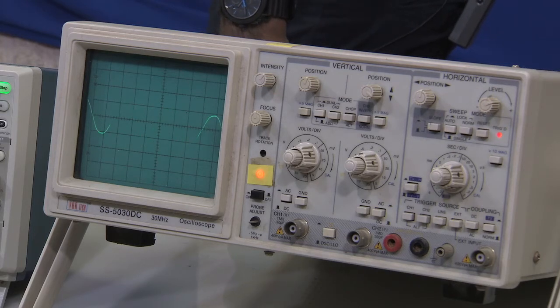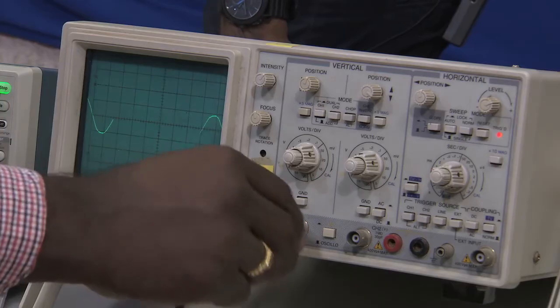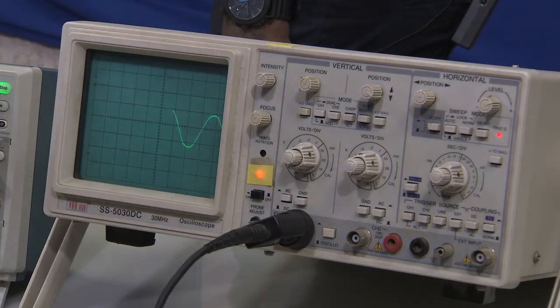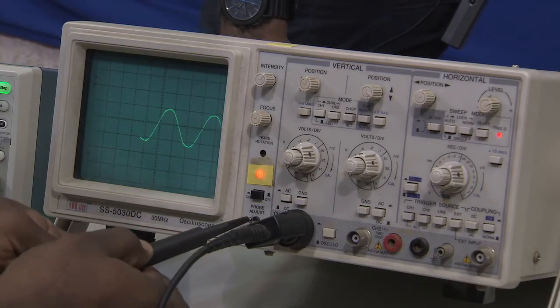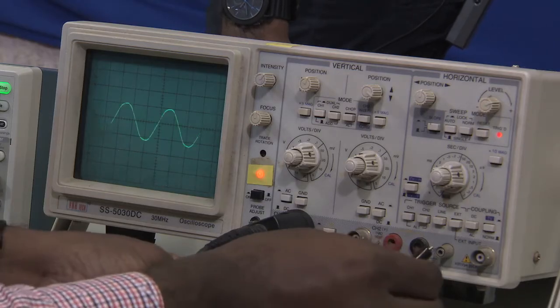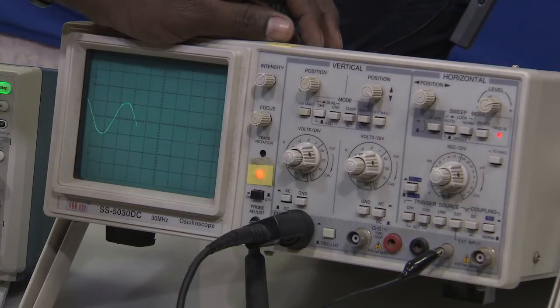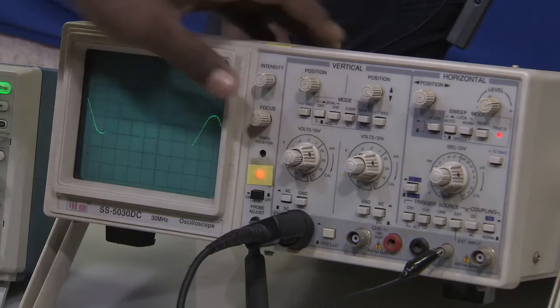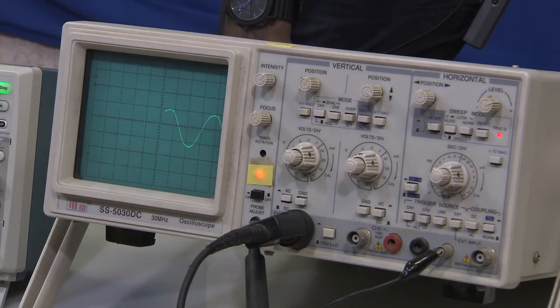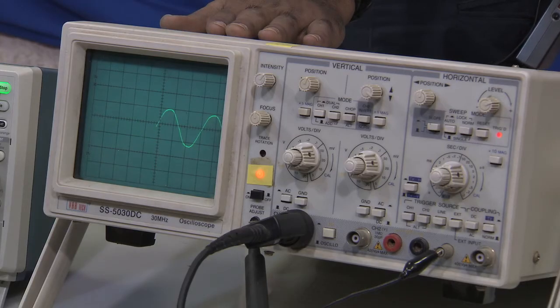Now, we can change the volts per division. Let us connect another probe to this oscilloscope. Here also we can do the testing of the probe. We are now connecting the probe, as you see the probe is connected, okay. Now we have to test the probe. There is a probe adjust, you can connect it there, and another one at ground, okay. Anyway, this is how you can connect and test the probe, alright. Do not worry about this, it is just to show that this oscilloscope also has the function for testing the probe.